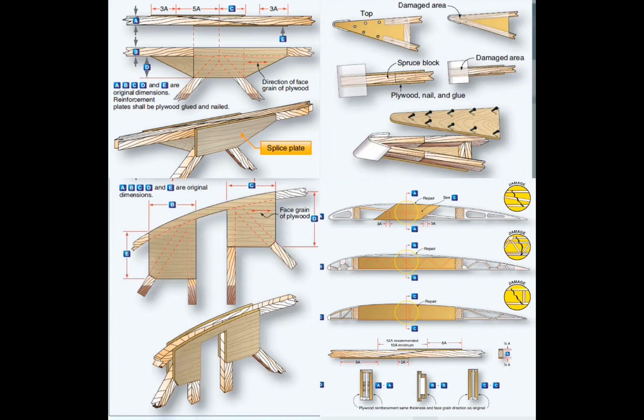What method is used to prepare plywood for bending? It is soaked in hot water and then placed in a form until completely dry. What are the results of using insufficient gluing pressure when making a wood joint? Thick glue lines, which indicate a weak joint.